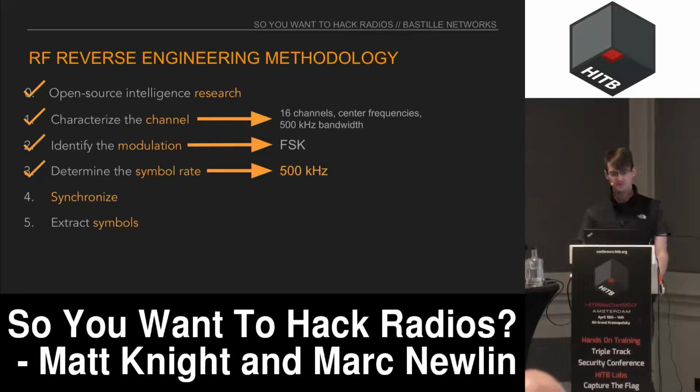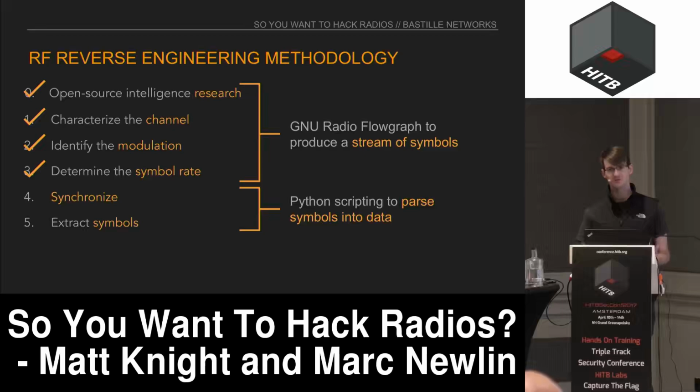So at this point, we've characterized most of the critical elements that we need to be able to translate what's happening in the wireless domain into bits on a disk. So we're going to take these first elements and turn them into a GNU Radio flow graph. It's going to produce a stream of symbols coming from our software-defined radio.